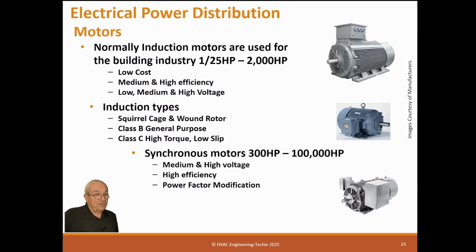Power factor modification. Now, I mentioned this before because of why we have induction in our systems, why power factor? Because in an induction motor, the voltage and current comes into the stator windings, and it induces onto the rotor. There's windings in the rotor, but they're not actually connected electrically. The induction just puts power into them and makes the magnets. That's what makes the motor turn, is that induction. Well, there's a little bit of a lag because induction takes some time, and that's what gives us these lagging circuits and inductive circuits, which cause power factor.